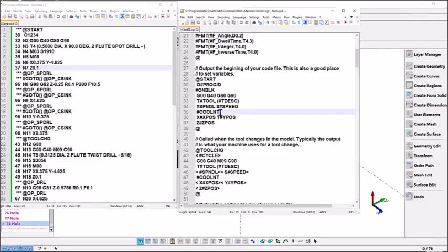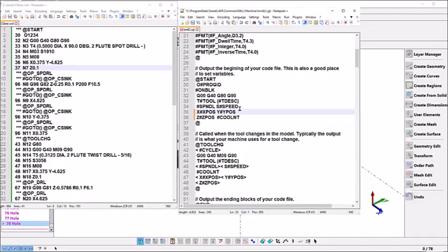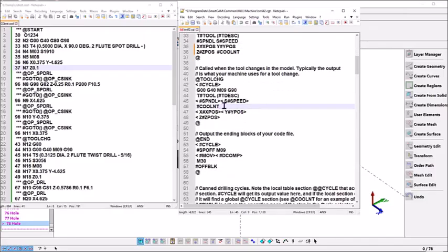So let's move this. I'm going to use Control X on Windows hotkeys and Control V to paste it there. And delete that. Then we want to do the same thing in that tool change section. If we go down here, that tool change section is doing the same thing, on line 47 there. We've moved it all down, but here it is again.